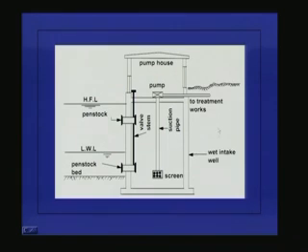For example, in this figure you see this is a river intake. Here we have the bank and this is the river here. It is almost inside the river, this intake, and this is the high flood level. My pump, or the pump house, should be above the high flood level to protect it from the flood damage. And I also have this low water level. My intake structure should be able to draw water even when the water is at a low water level.